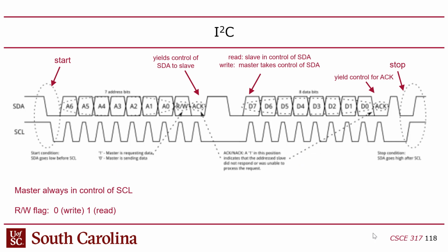Okay, so here's what the transaction looks like. It's an open drain. So remember, if no one's talking, the default state of both those wires is going to be a logic 1 because of that pull-up resistor. No one's pulling down. The pull-down transistors all have about a mega ohm of resistance when they're turned off, so you have a bunch of mega ohm resistors in parallel to ground, but to VDD you have a 10,000 ohm resistor going up.